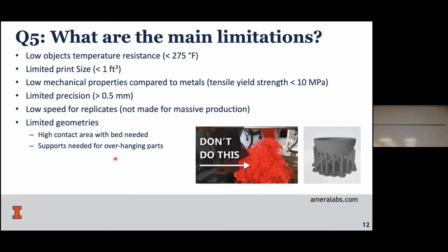So what you need is to create artificial supports. That's what we call supports, and it's what we see rotating on the image here. You need more plastic, you need more time, and after, you need time to remove all these small supports attached to your item. That could be a problem if you're aiming for certain geometries. Let's say I want to print a brain. To make it hold, I need to create a fake structure underneath. This thing is discarded, it's lost plastic, but it's needed to make sure that when you print it, you have good stability and you don't end up with a big blob of filament.